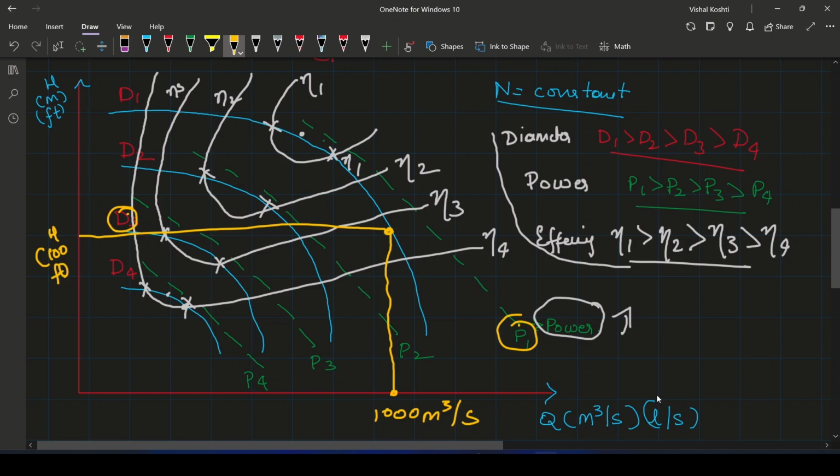That trimmed impeller can be machined to suit our requirements, and we can also modify the discharge as well as the head from it. Those calculations, which we'll find out using the pump affinity laws, and some basic calculations, we'll be dealing with in the next video.